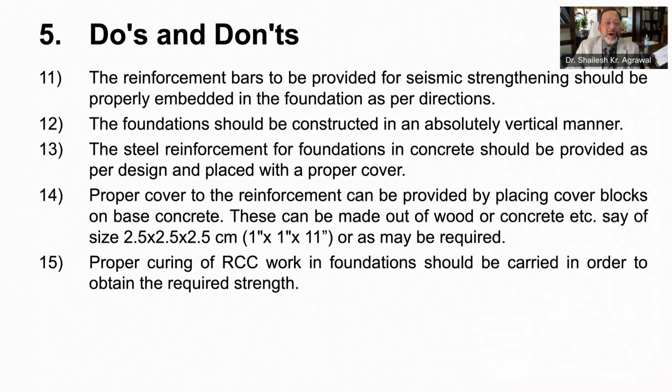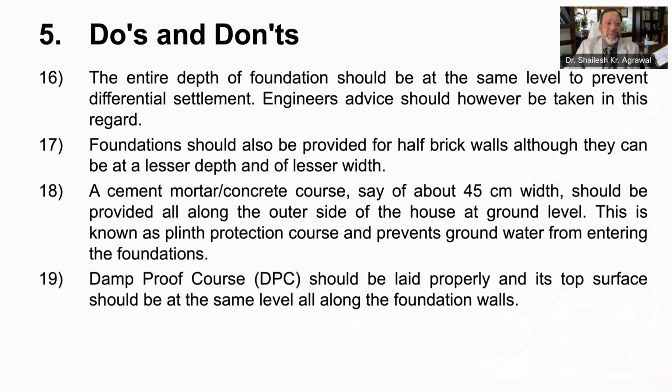Proper curing of RCC work in foundation should also be carried out in order to obtain the required strength. The entire depth of foundation should be at the same level to prevent differential settlements at a later stage. Engineers are advised to take care in this regard. Foundations should also be provided for half brick walls, although they can be at a lesser depth and of lesser width.